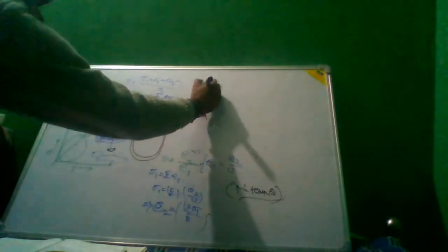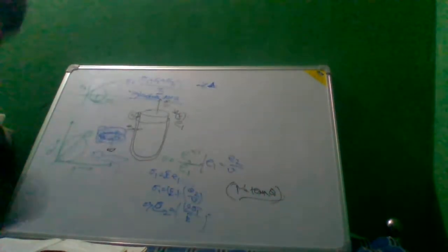And as I was saying, there are three parameters which are going to be changing, that is E1, E2, E3, and the hydrostatic stress, which is sigma 1 plus sigma 2 plus sigma 3 by 3. There is a constant, known as the bulk modulus, so K, taken as the bulk modulus, into the dilation is equal to sigma.